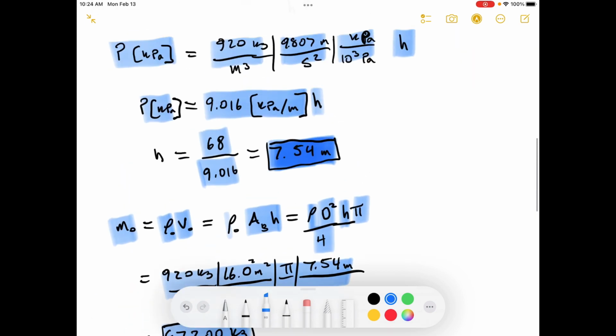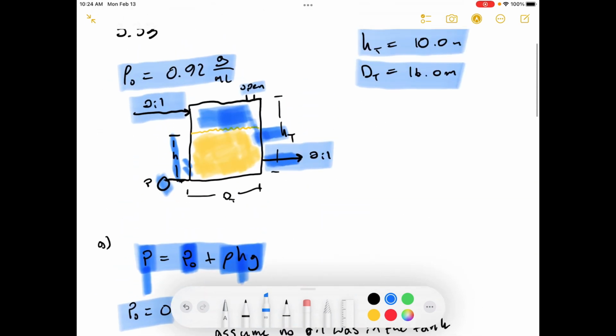And remember I said at the beginning that if that level drops too low, you could end up sucking out some of that extra head pressure gas in there. So if that pressure builds up too much of gas, then you'll end up sending gas out with your outlet because that level will artificially drop too low. And depending on your process, that could cause problems down the line.